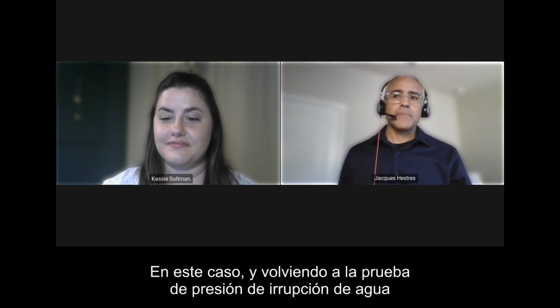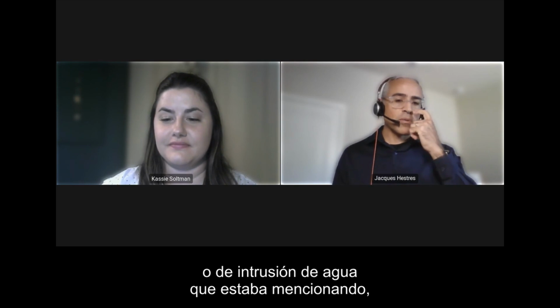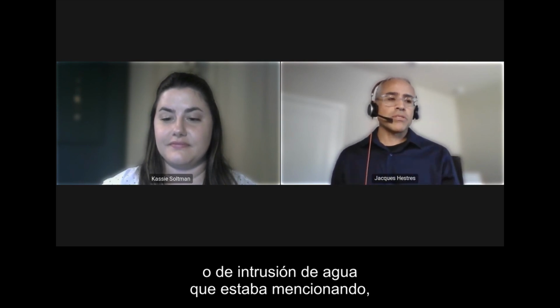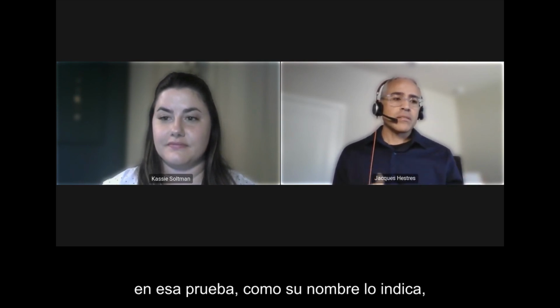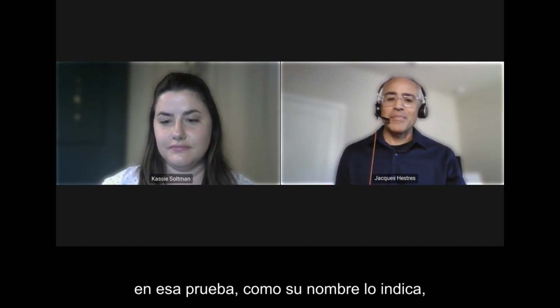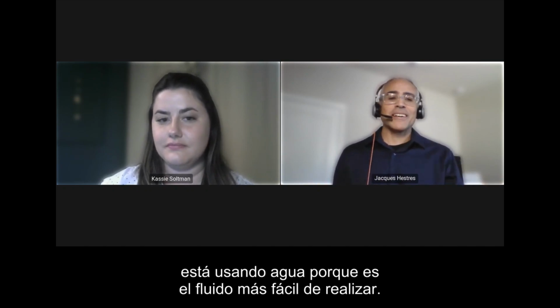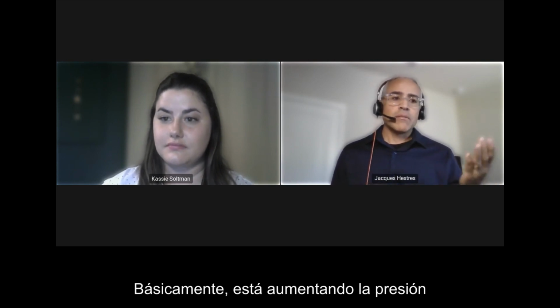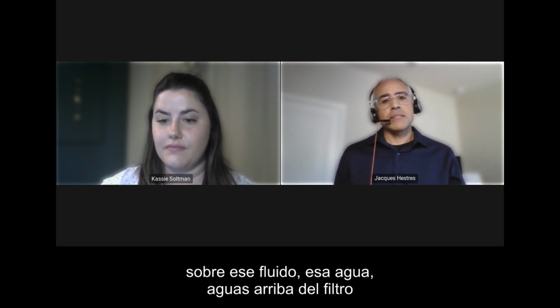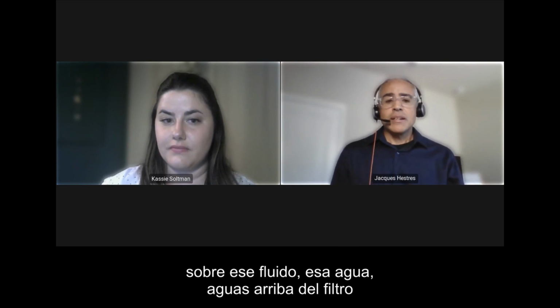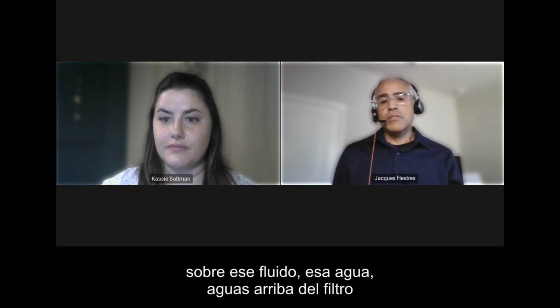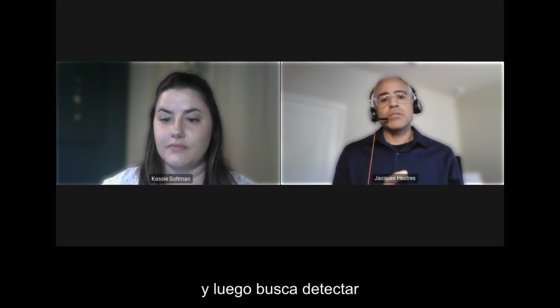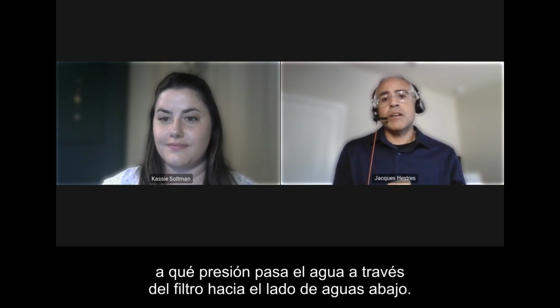Yes. So in this case, going back to that water breakthrough or water intrusion pressure test that I was mentioning, that test, like the name implies, uses water because it's the easiest fluid to test with. Basically, you're ramping up the pressure on that water, upstream of the filter, and then you're looking to detect at what pressure that water is passing through the filter to the downstream side.